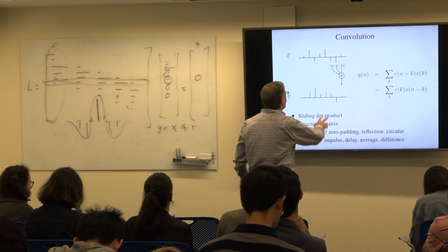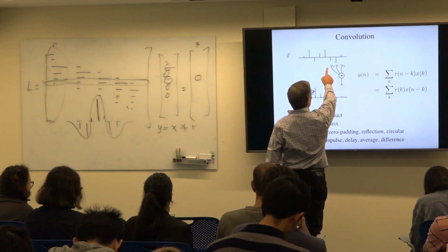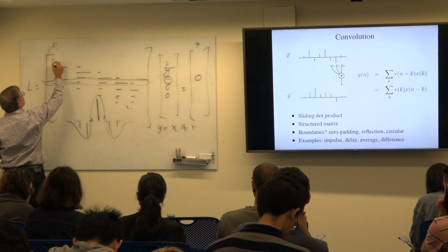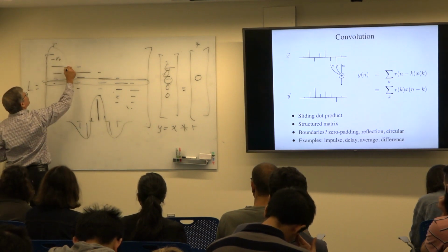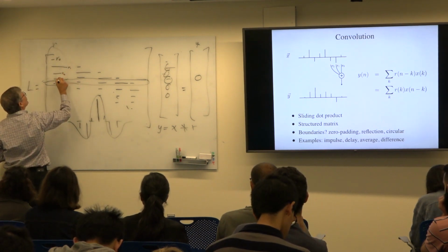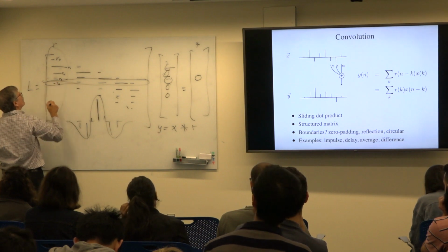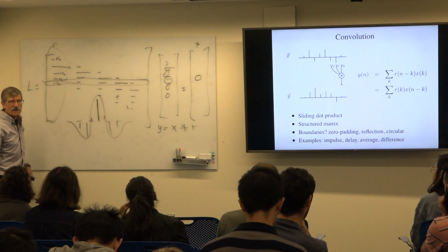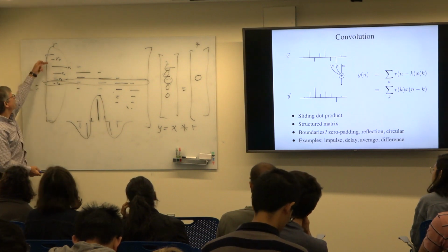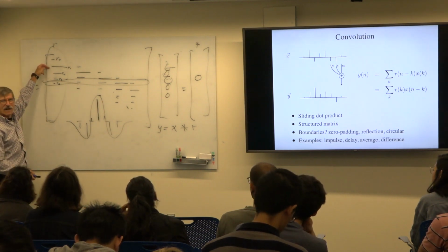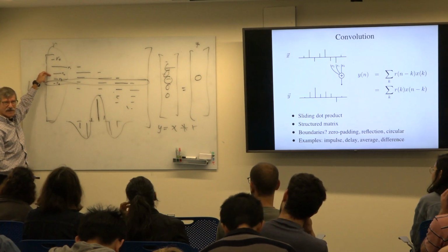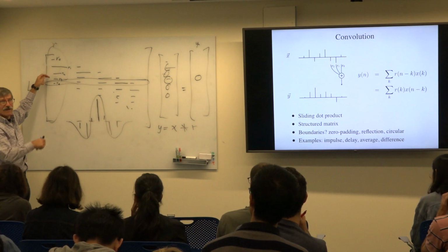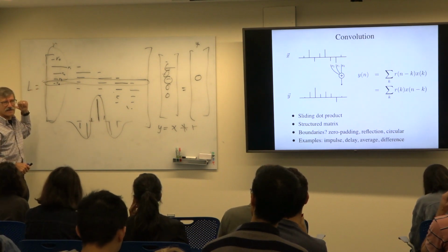So you'll notice that the numbers are going backwards because it's convolution. When we did it as an impulse response, if I wanted to label these little dots, this is R0, this is R1, this is R2, this is R3, this is R4, right? The numbers are going up here because if you kick it at time 0, this is the output at time 0, the output 1 time step later, the output 2 time steps later. This is causality. When you kick it, you only get results in the future. You can't kick it and have that affect the past.